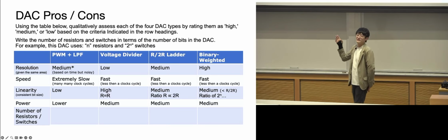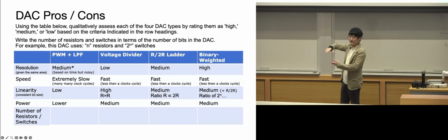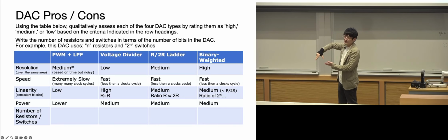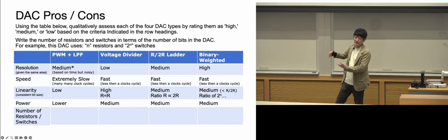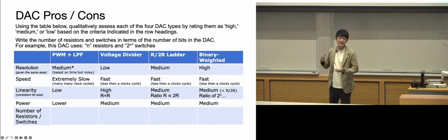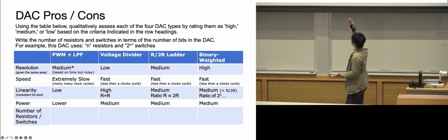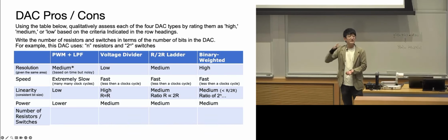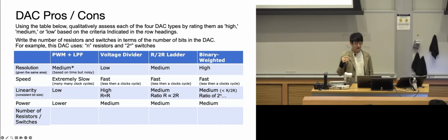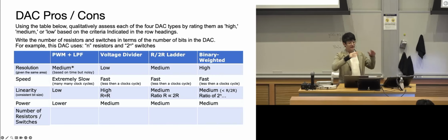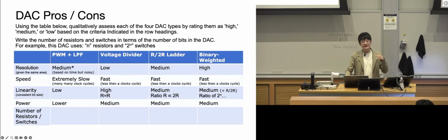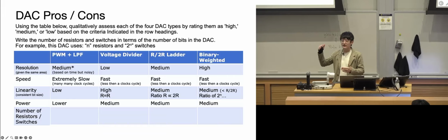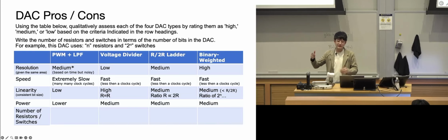It's going to be 2 to the n, because you essentially just convert your n-bit decoder into one resistor per bit. So 2 to the n for both switches and resistors. For the R-2R, how many would that be? Yes, pretty much. It's 2n plus 1 because there's one down there. But yeah, so roughly 2n. And then n resistors, because each one corresponds to essentially one bit of the DAC output.